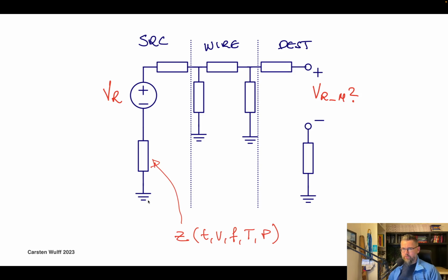And in a real integrated circuit, this ground will usually be off chip. Even on the PCB, the ground will not be perfect. There are going to be resistances going all the way from different points on the circuit to this point. There's an impedance there, and it can depend on time, on voltage, on frequency and temperature, and on process. So if on one part of the chip we create a constant voltage, and we want to distribute that across the chip, that is actually very hard, and sometimes you just have to do that. Sometimes you cannot do the alternate route, which I'll explain in a moment. But sometimes the accuracy requirements for this voltage are such that you can't do anything but make sure that it becomes the same voltage on the other side.